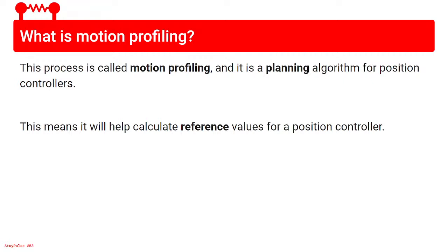I don't understand it. So the feed forward just takes in the speed of the thing, right? And then calculates some voltage. Yeah. And then PID also takes in that speed, and then you combine the two together. For a position though, you're going to calculate the rate of change of the position set points and feed that into feed forward. Rate of change of the position set points? Yeah, that makes sense.